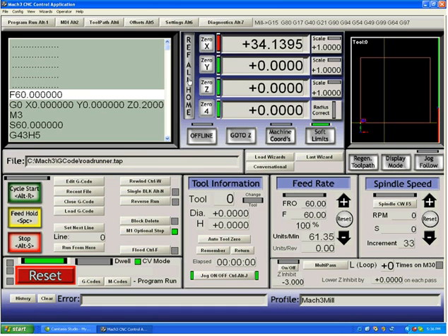The Y begins to go to the switch, comes off of it and stops. The X goes to its switch, and when it hits it, it reverses direction and stops. And you'll notice it instantly flicked back to 0. Our system is now 0 in machine coordinates. If I regenerate the toolpath, here we are zeroed again.